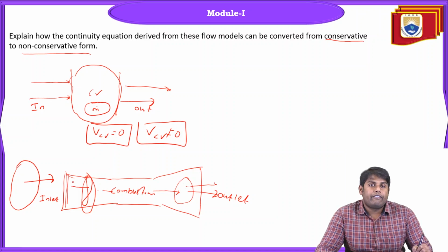So at each and every state, the thermodynamic variables, basically pressure, temperature, velocity, density, are changing at different stations. If you consider this total engine as the control volume, it is covered by boundaries. So basically you can see this is a boundary, where you have flow in, flow out. When the flow is getting in, there is a thermodynamic change. When it is getting compressed, there is a thermodynamic change. When it is entering the combustion chamber, there is a thermodynamic change.